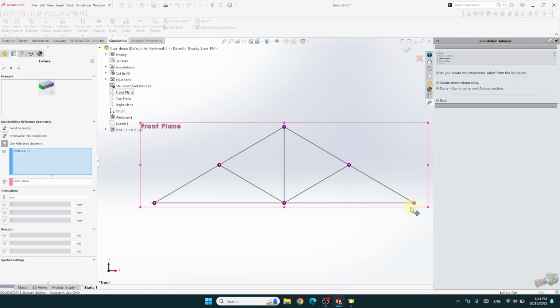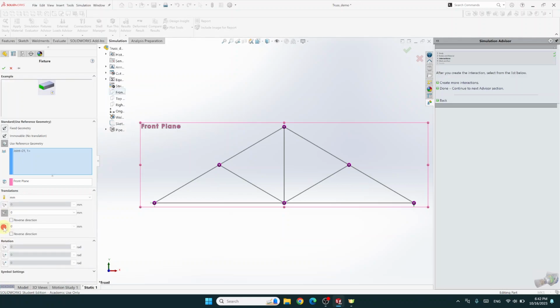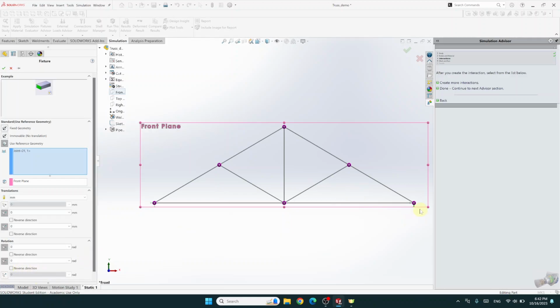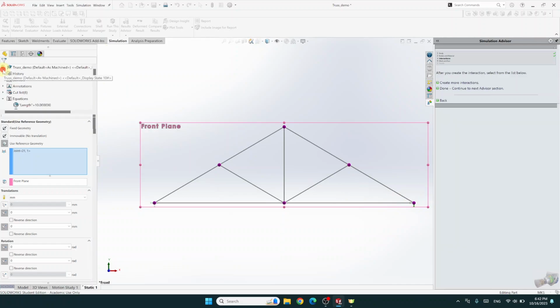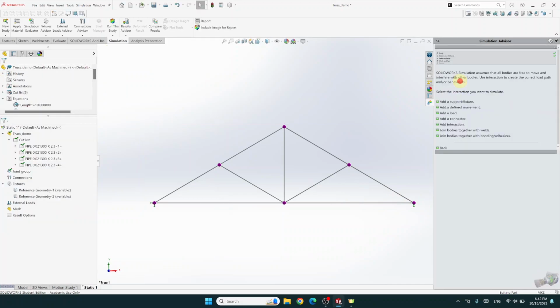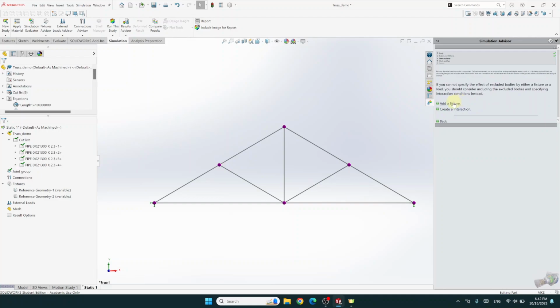And for this one is the normal connection. So the translation on the x is free. So x highlighted gray, so it's free. This one I stop, this one I stop. I know it can go up, but you don't want it to go down, so you put it at 0. Rotation 0 on x, 0 on y, and the z it can rotate. So here we can slide and we can rotate. And you click enter.